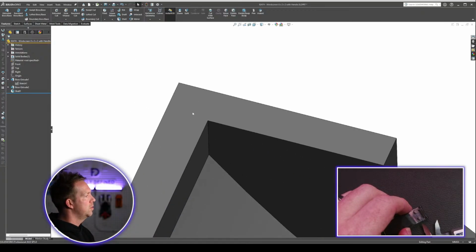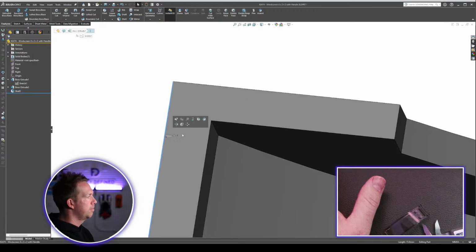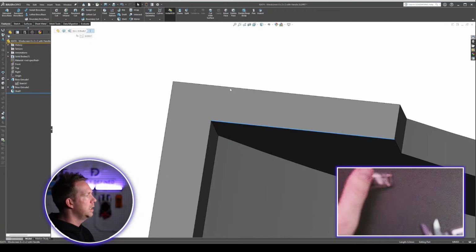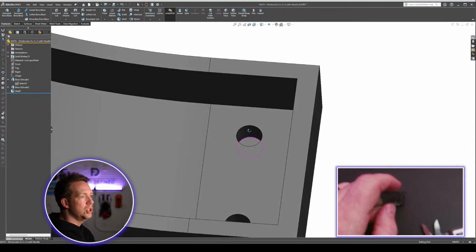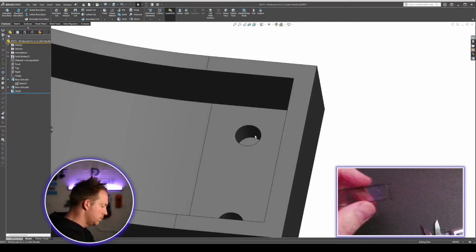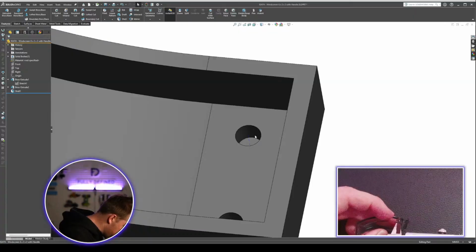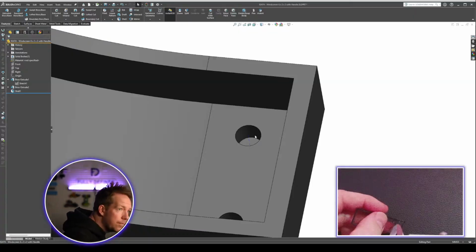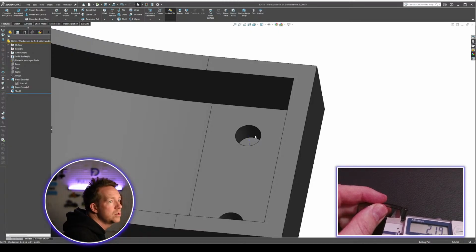All right. It's pretty small. But yeah, from here to here, 1.5. Here to here, 1.3. Now, place where we can check that thickness is these holes. So I can measure internal diameter of that hole. Let me make sure I get the right thing. I'm getting 2.2.